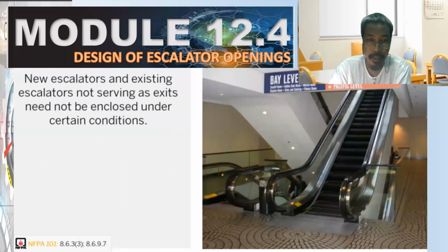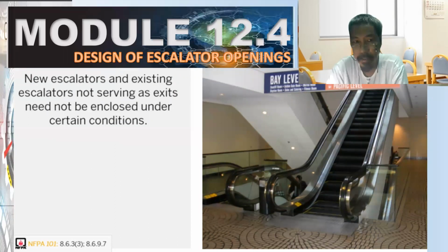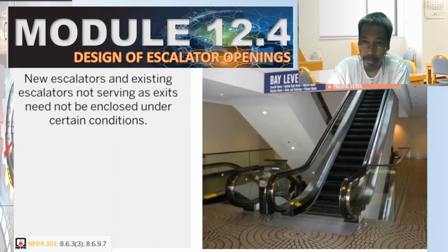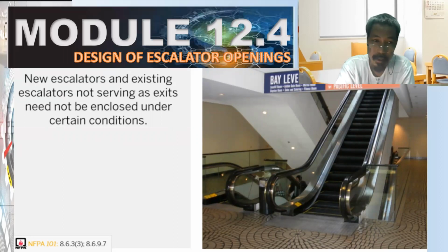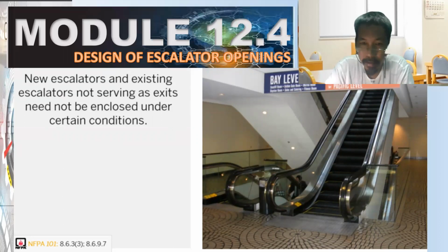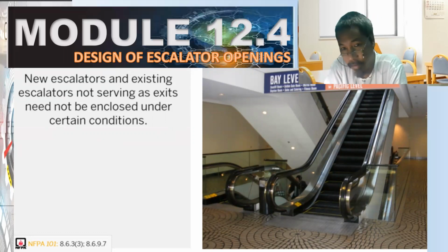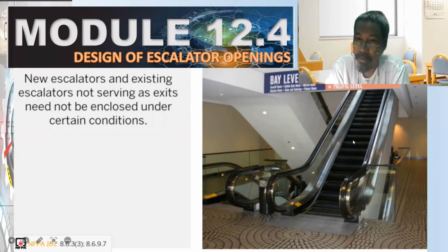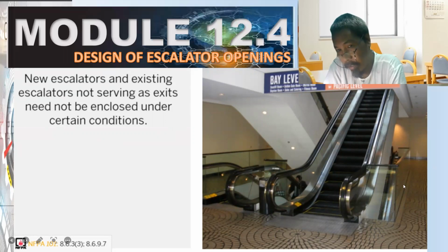Another is design for escalator openings. New escalators and existing escalators not serving as exit need not be enclosed. If they are not considered an exit, there is no need for enclosure under certain conditions. Usually we have this type of escalator in our malls, with only a provision for occupant safety here, a fence.